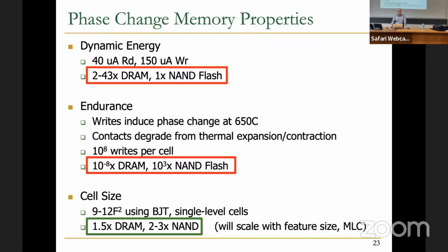So for DRAM, we don't actually know the endurance because there is no report for that. We don't know if DRAM has an endurance problem or not. At least we haven't observed an endurance problem of DRAM until we use our system. At some point, you just wear out your whole system as well. But at least from what we can see, the DRAM architecture doesn't have the kind of issues that can cause endurance problems. But in PCM, clearly we have that problem.